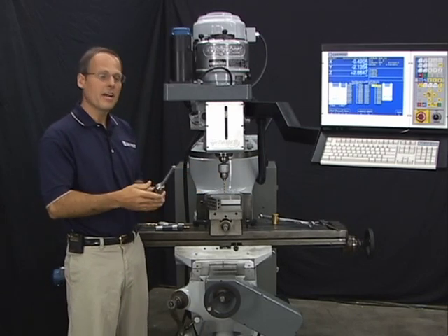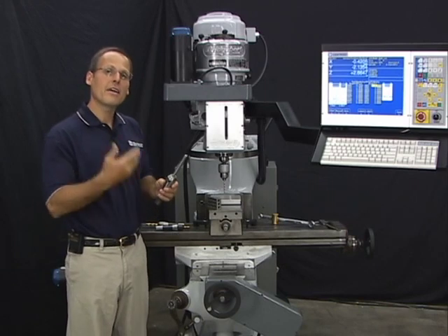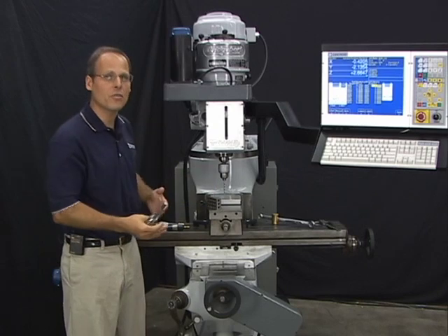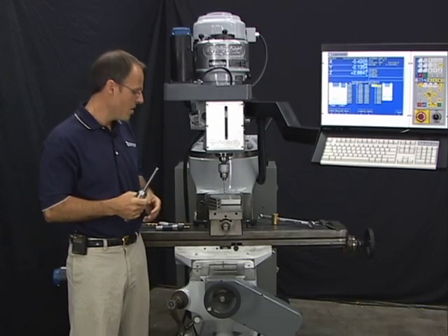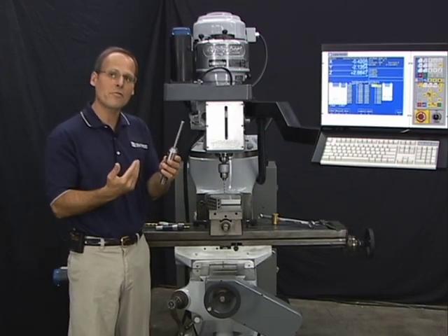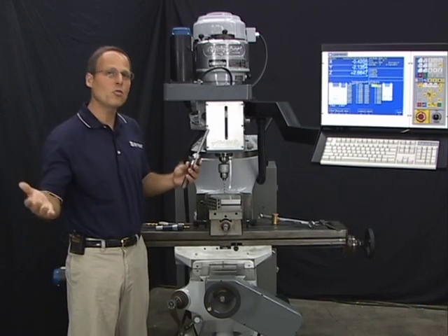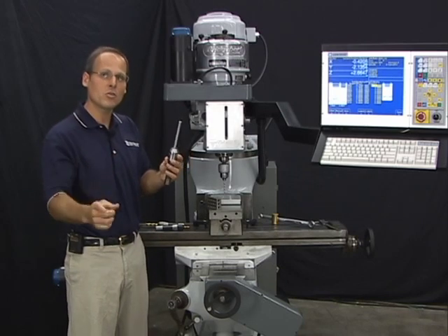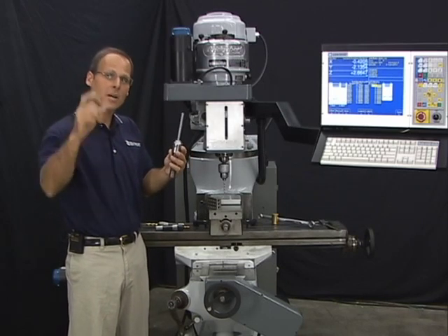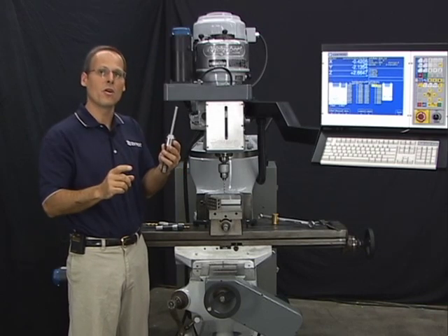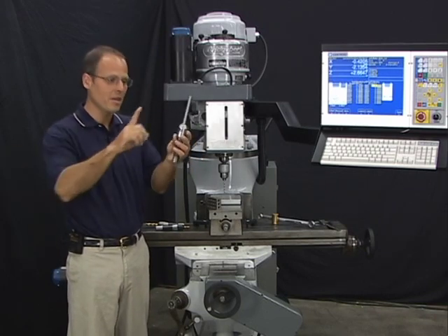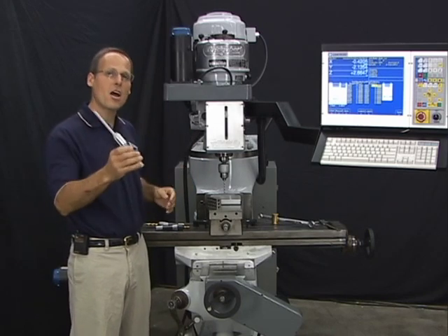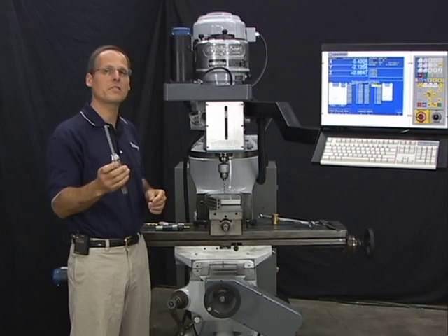Another advantage is, out of these 5 tools that I set, if I break one of them, with the old method, if you break any one tool, you have to reset all your other tools because they're relative to each other. With our method, they're all measured off the reference tool. So if I break one tool out of 25 that I'm using, all I have to do is remeasure just that one tool when I replace it against the reference tool. All the other tools are still the same, still measured off the reference tool. I don't have to remeasure them. So you've got a big time saving advantage to going with the reference tool method.